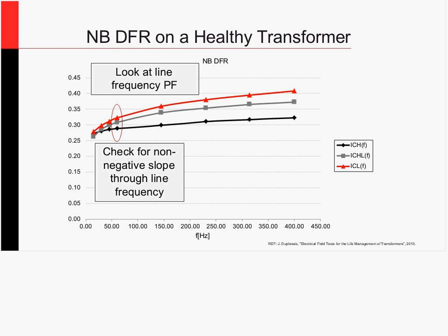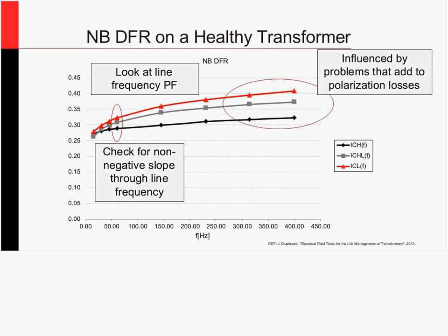And then the next thing you're looking at is what I call the tail of these curves. It's expected that as frequency goes up, the power factor is going to increase, but you don't want this dramatic increase in power factor with frequency. So you're just checking to make sure that this isn't shooting off to the sky. If it is, then that's going to be influenced by problems that are adding to polarization losses. And so then you have a little bit more information on how you want to go about exploring that.